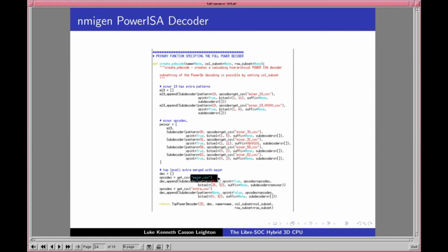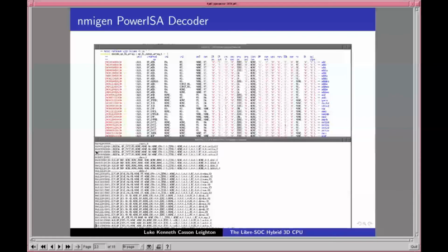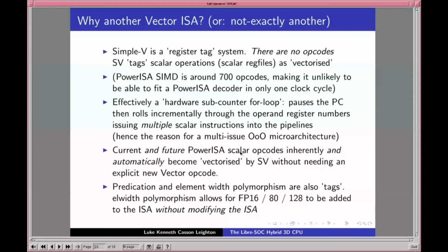That contains the major opcodes, and it's based on bits 26 to 32 in Power order, etc. You get the idea. And then once that's decoded, one of the switch statements goes further into the hierarchy of further decoding, and ultimately you end up with one and only one of these lines being activated, and you've decoded the operand, decoded the instruction.